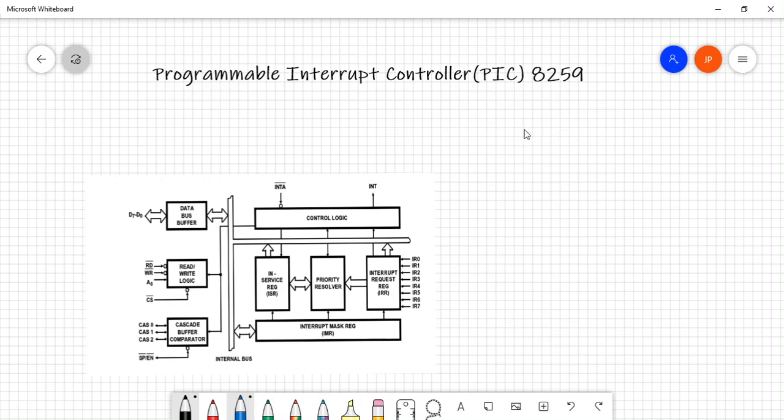So we already know in 8085 this is an additional chip that we can connect. In 8085 we actually have 5 interrupting pins, which are the hardware interrupts. You have your TRAP, RST 7.5, 6.5, 5.5, and finally you have your INTR pin, right? Now you know that all the 4 interrupting pins, TRAP, RST 7.5, 6.5, 5.5, are vectored interrupts. We have already discussed what a vectored interrupt and a non-vectored interrupt is.